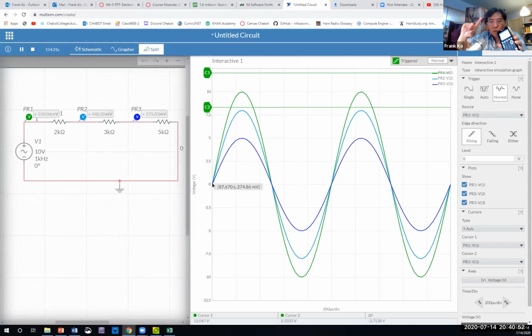There's a quick 2-button push to convert time into frequency. You hit your reciprocal key, 1 over x, and then you hit equals. And what is the frequency that you calculate, Gregory? 1 kilohertz. 1 kilohertz. And does that confirm our source frequency at the very beginning? We said this would be 1 kilohertz, and we got 1 kilohertz by measuring right off the display screen.